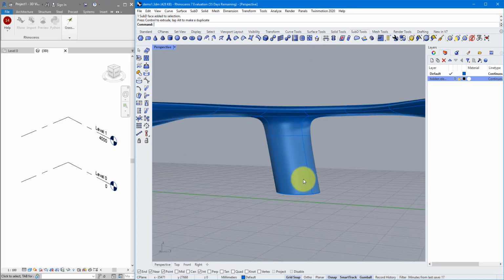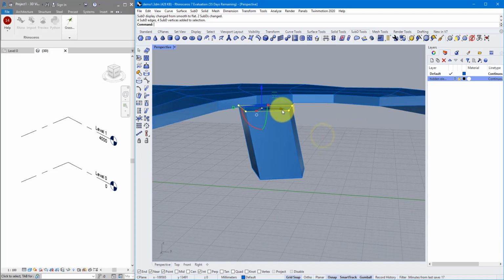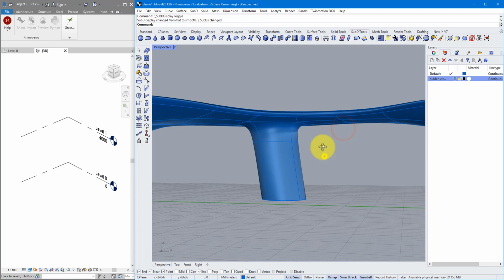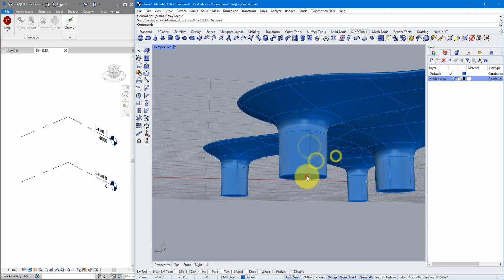Sometimes if you make this one slant too much, it may feel like there's no longer a smooth transition there, or at least not natural. Worry not, you can simply switch to the mesh appearance, get those lines, and move them slightly in the same direction. Now that's a lot more natural to me. Let's do the same 4 more times.